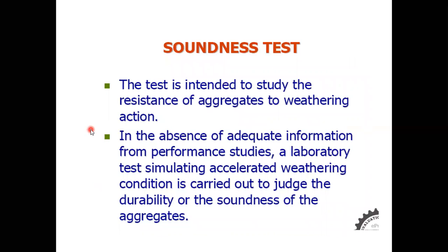Next is the soundness test, that is the durability test. The purpose of conducting this particular test is to study the resistance of aggregates to weathering action. All these things we discussed in the starting while discussing desirable properties. In the absence of adequate information from performance studies, a laboratory test simulating accelerated weathering condition is carried out to judge the durability or soundness of the aggregates.